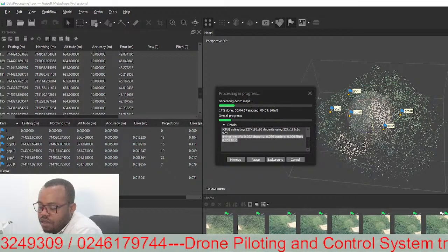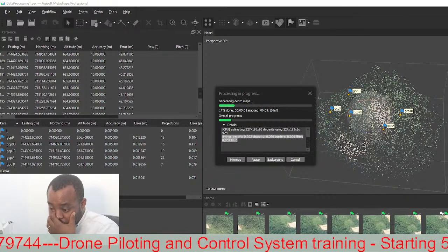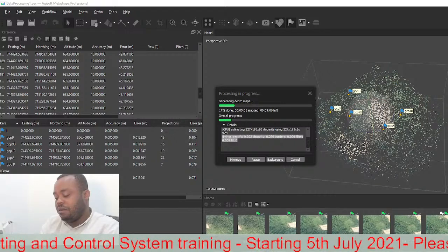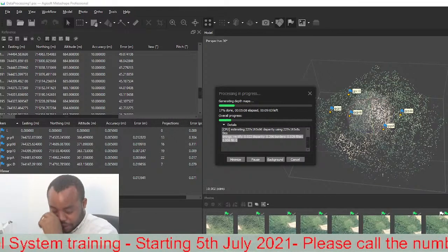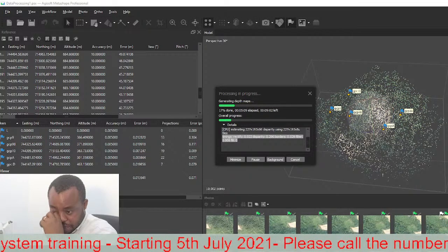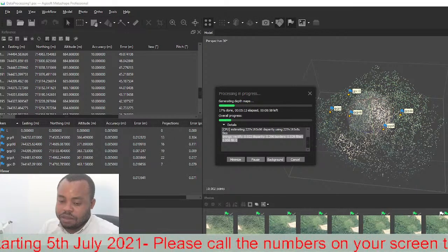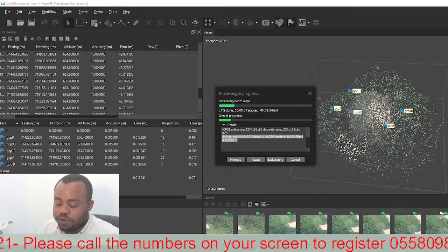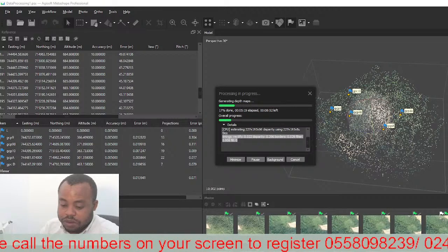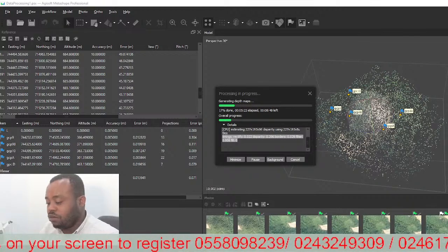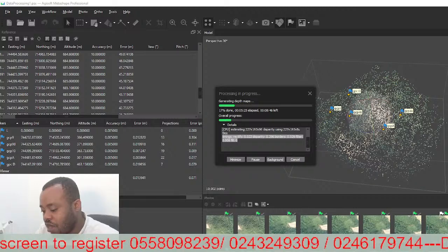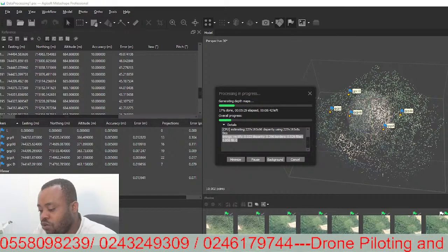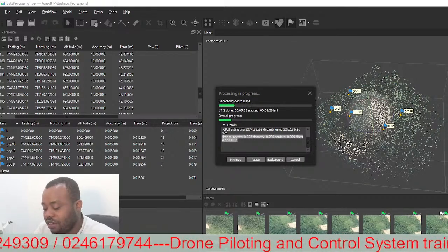A very interesting question by Foster. So the machine specs that you will need: mostly the manufacturer comes with its recommendations, and these recommendations are based on the manufacturer's statistics based on the software's resource demand. I would say that you should first focus on your graphic card, second your processor, and then third your hard disk space and your hard disk technology.